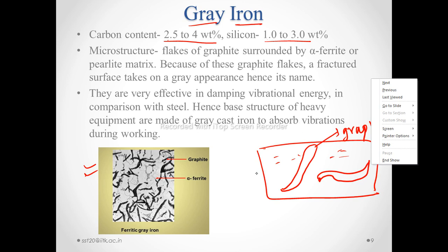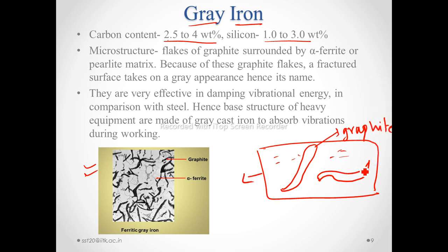When we apply force in the form of tension, these pinpointed edges of the graphite will act as stress concentrated areas. So they are very good under compression force.